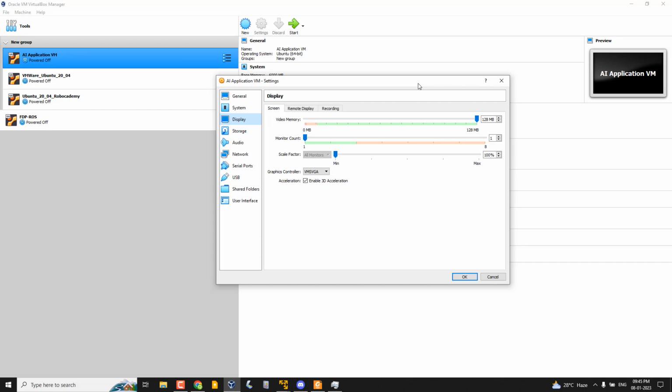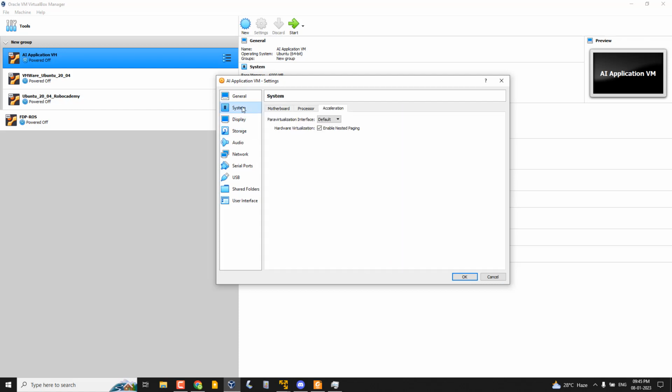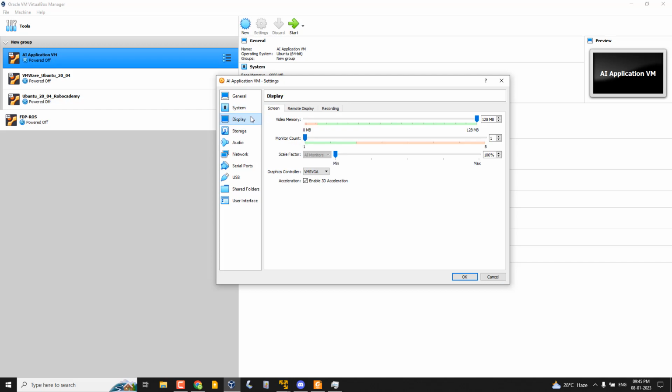Obviously we will get the settings in this green range, and the system performance will degrade if we have bad graphics settings, or if the driver of the VMware virtual machine is not installed properly. That can also be a reason. But if there is any unknown reason, I'm not sure, because you are actually working with a very high-end PC. Ideally it should work.